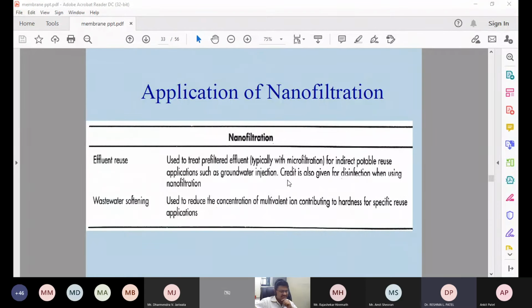Carbonates, bicarbonates, chloride, and sulfates are the anions. Carbonate and bicarbonate hardness we can precipitate by boiling. The rest we need to remove by these types of treatment when we are using the water, especially for industrial purposes. So generally calcium, magnesium, whatever the divalent and more than that, multivalent ions like Ca2+, Mg2+, Al3+, Fe2+, these cause the hardness.